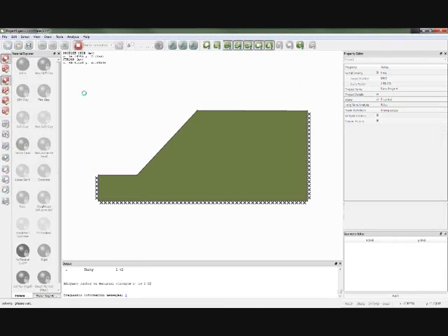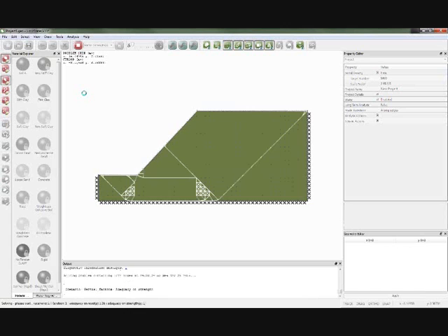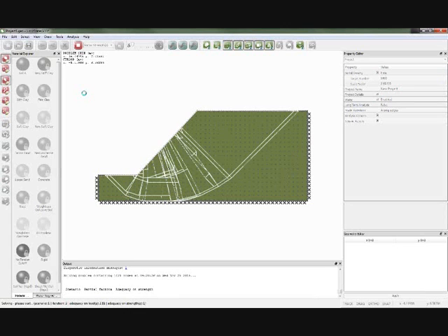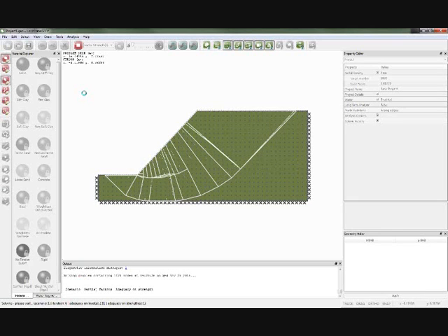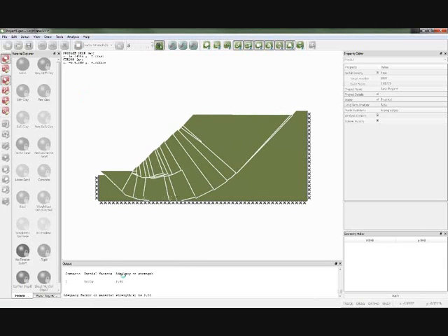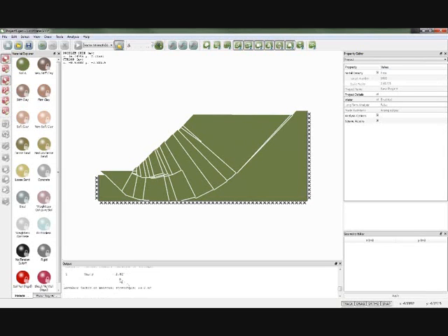And what you'll find is if you solve there, the solution will take a little longer to get there, but it will be more accurate. And what we recommend is when you've come up with your final refined model that you just increase the number of nodes and check that the factor on strength that you're getting from the solution doesn't change significantly as you've upped the nodes. So here we've got 2.81 for this one. The previous solution was 2.82. So in fact, there's almost no change there. For this particular problem, that number of nodes is going to be perfectly adequate to give us an accurate solution.